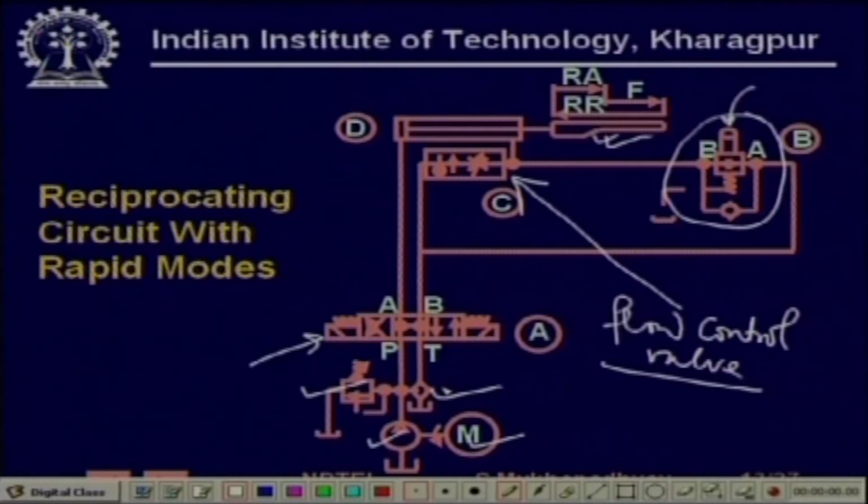Next you operate it, let us say you operate the left cylinder. Okay, first let us look at the advance circuit, which is the right cylinder. If you connect it, then port A gets connected to pump. So, the fluid flows when this coil is energized. This is for extension, and this is for retraction.